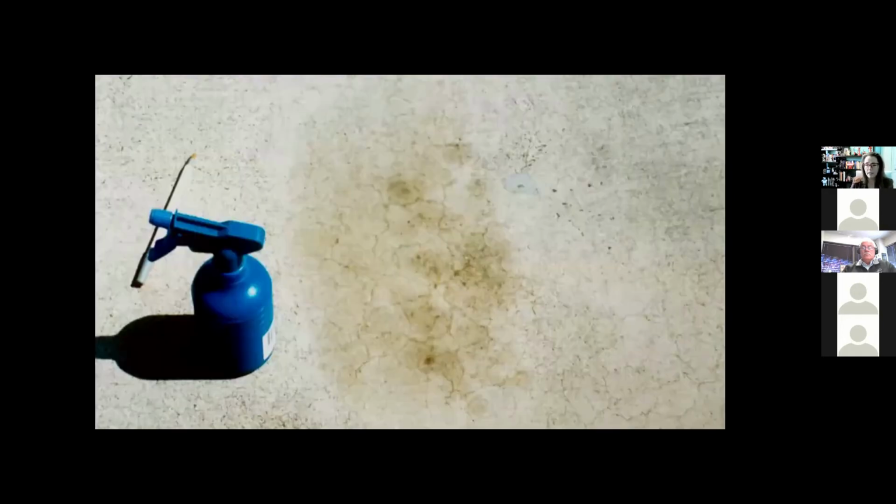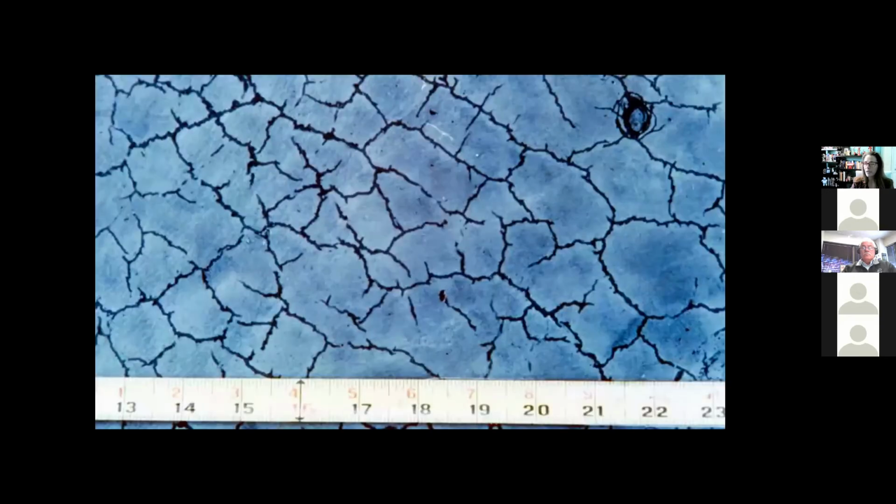Again, with crazing, you're not going to see it unless you look closely. If you're out there in the field, well, maybe some of you have better eyesight than me, one thing you can do to show it, if you need photos, is to spray some isopropyl alcohol on the surface before you take a photo, or if it's rained, go out that day and inspect concrete. You're going to see a lot more on a rainy day than you would on a nice, beautiful sunny day.